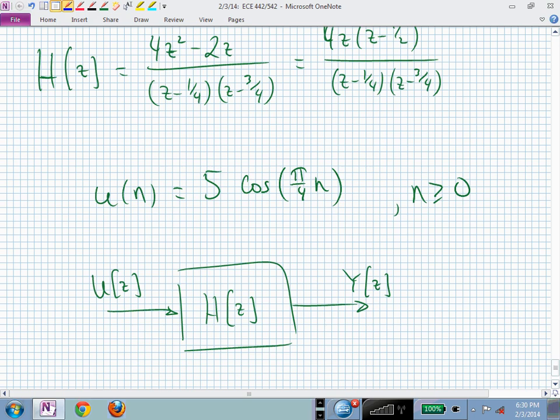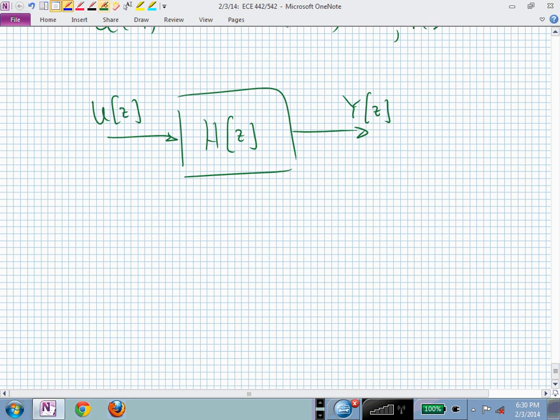Now we know our relationship between S and Z. I know you guys are still thinking about 12th order. But what do we know about Z and S? This could be a give me on the exam. Right? That's a unit advance. Or Z to the minus 1 is e to the minus S capital T, where T is our sample period.